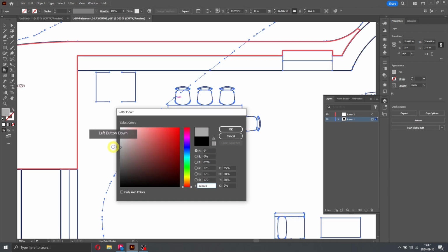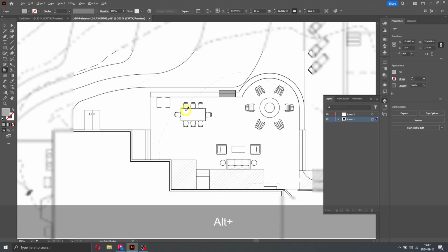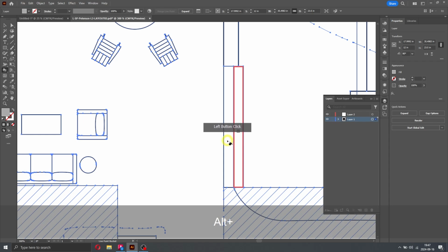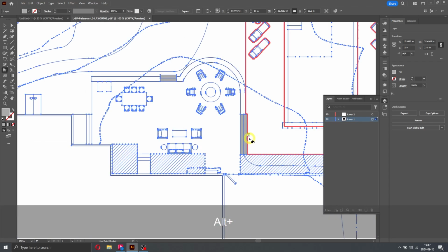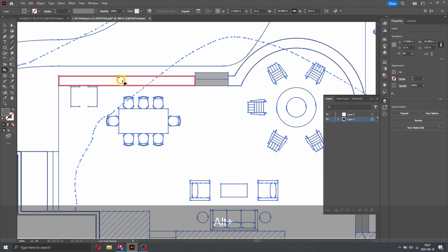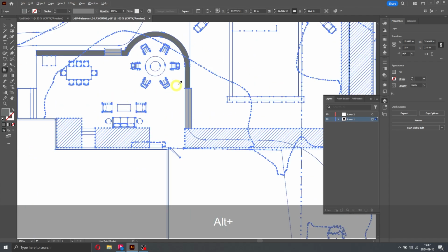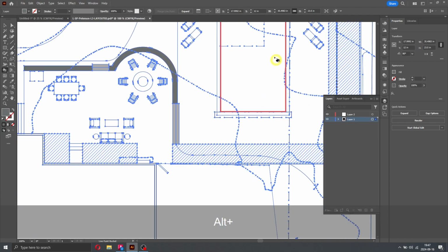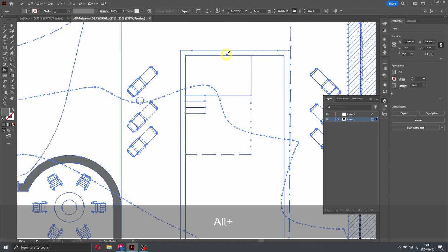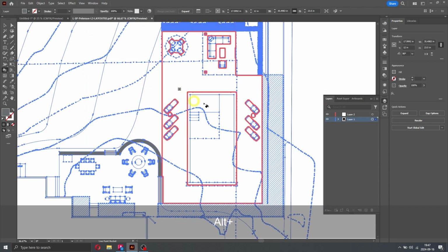I can, for example, these are steps. Let's make our steps light and our caps a little darker. I can just start filling these in. So very handy. This is just like the magic wand selection tool or the fill in Photoshop. So I can just go around, let's change our caps to be a bit darker. So I can start filling all of this in. Again, you might run into some places where you have little gaps or enough line work covering it that you have to select on both sides. Let's see if I've got any of those around here. Doesn't look like it. Actually, we'll probably see some of that in the lawn.